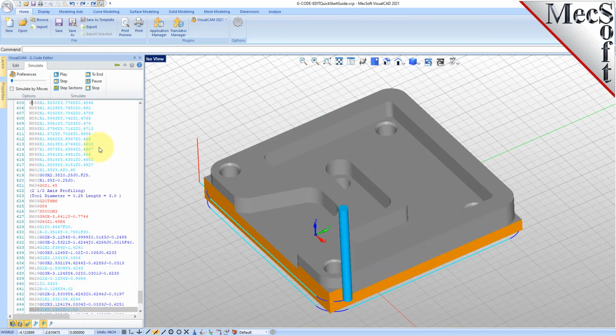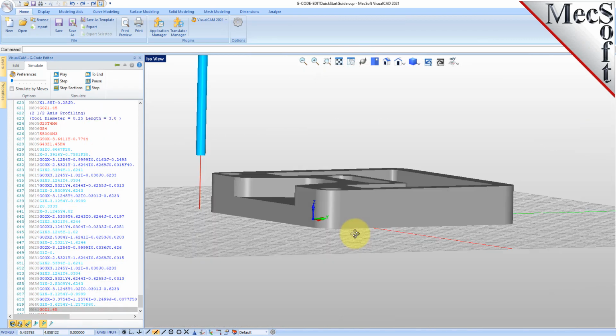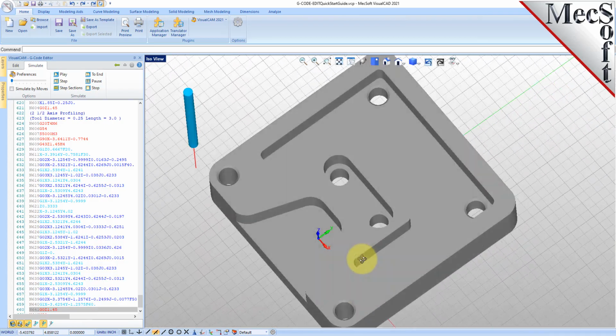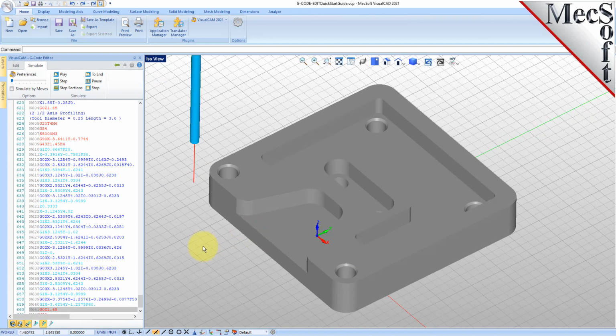Now that's pretty cool. You can see your actual model that was created just from the G-code file. Again, I mentioned previously that you don't have to have a part file. If all you have is a G-code file, you can load it and just define a stock, give it a large enough dimension so that it encompasses your toolpath, and then you can perform a cut material simulation.